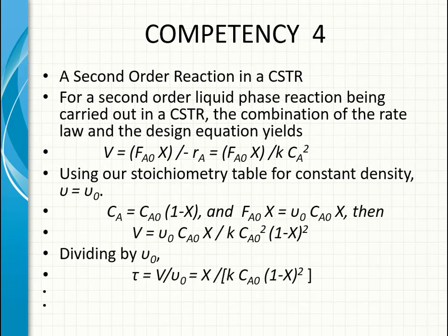A second-order reaction in a CSTR. For a second-order liquid-phase reaction being carried out in a CSTR, the combination of the rate law and the design equation yields the volume equal FA0 times X divided by minus rA. This is equal FA0 times X divided by k CA squared because it's a second order.